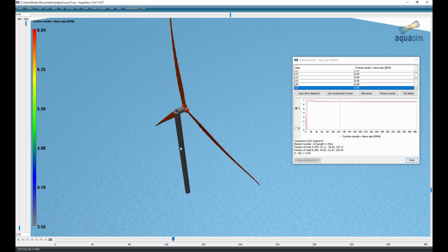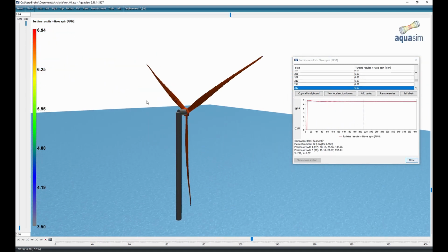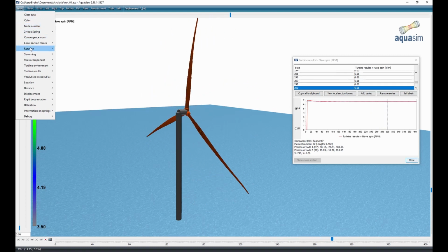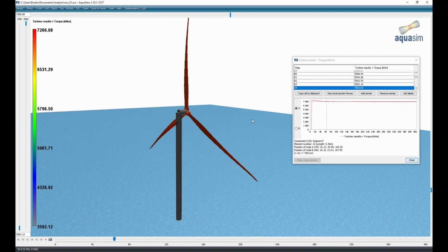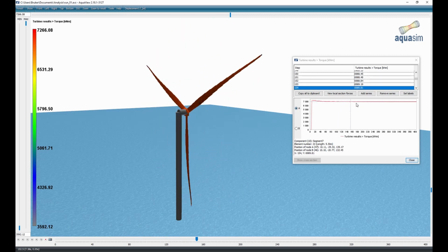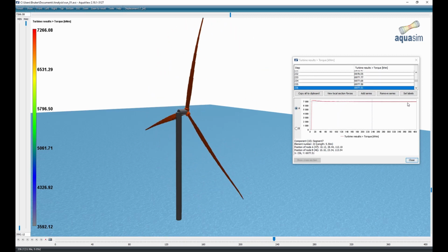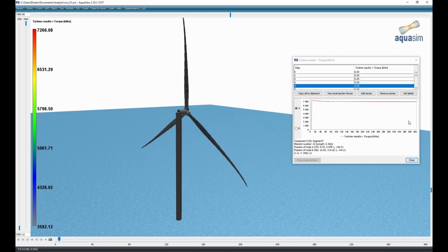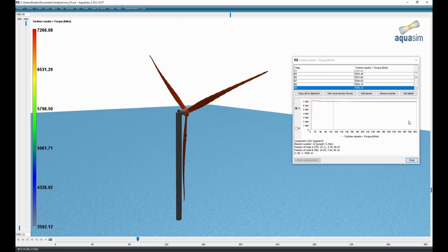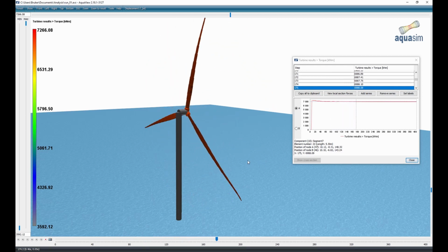Another parameter that is interesting is the calculated torque. This is also found under Turbine Results. The torque shows the same trend as the velocity, it stabilizes around a certain level. In our analysis setup we chose a wind velocity profile that was flat and constant both in time and in space. So, the trend in the result plots corresponds well with this.